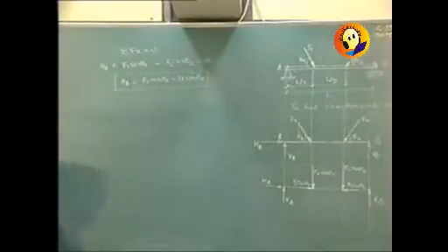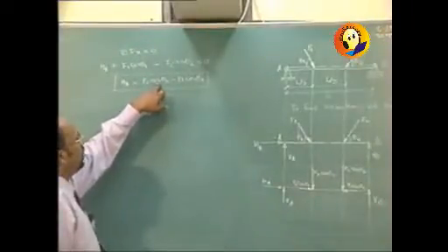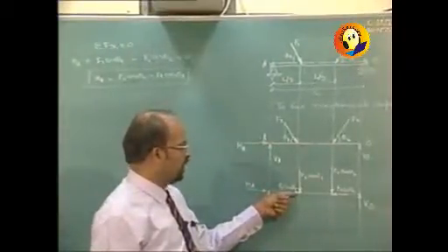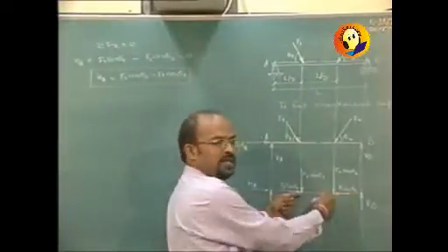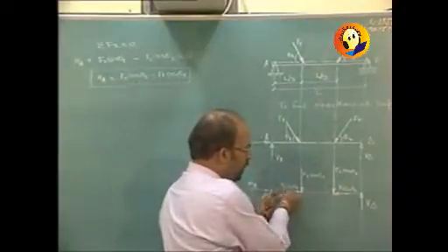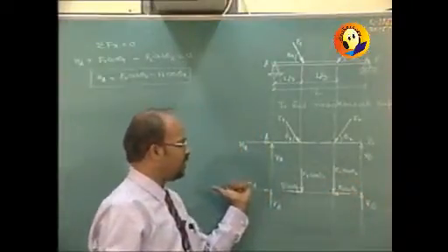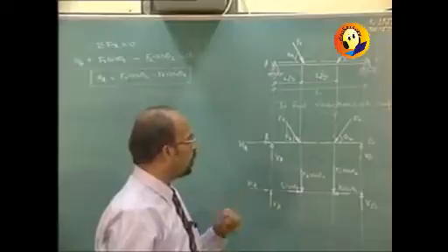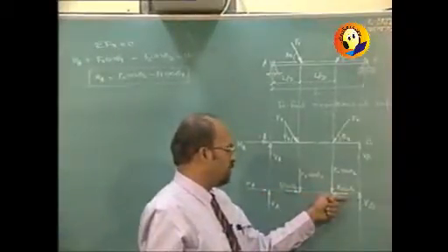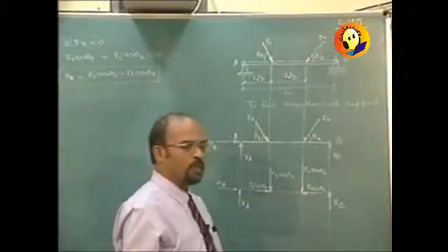Now of course here, if F1 cos theta 1 happens to be greater than F2 cos theta 2, observe the figure: if this horizontal force over here is more than F2 cos theta 2, resultantly this force will be more than this, effectively the beam will be pulled towards right and the reaction should be towards left. So our assumed direction will be wrong. So I repeat, if F1 cos theta 1 is greater than F2 cos theta 2, in that case there is a net force acting towards right, HA should come out to be negative.